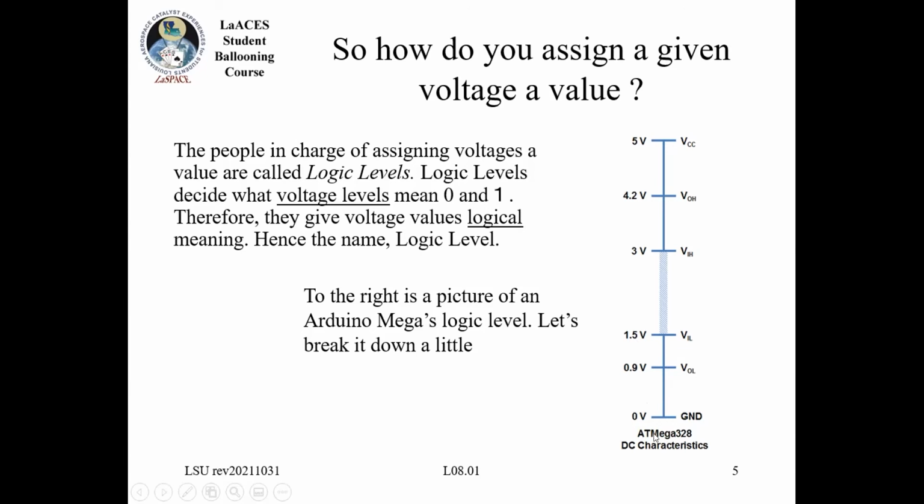So you can see if I had two slightly different logic levels, I should be able to look at the two sets of these values and figure out, hey, is the high output from this other one going to be correctly interpreted as an input high on this second piece of electronics, right? Normally, you try to work all within a common logic level system, if possible, so you don't have to worry about that. But if for some reason you have to, this would be how you would figure out if they're compatible.